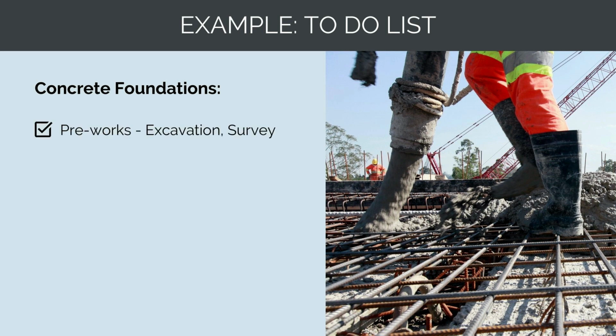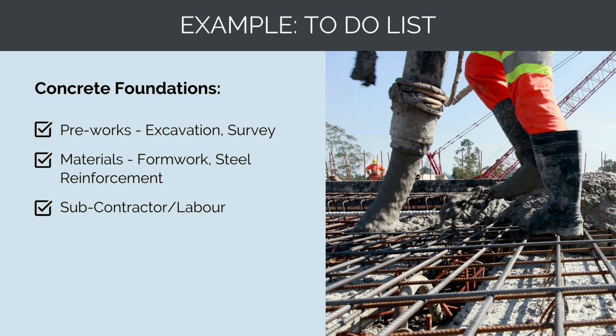So your pre-works, your excavation, you've got to make sure the subcontractor comes to site, or that you coordinate with your supervisors and foremen to make sure that excavations take place as planned. You'll need to call up the surveyor and organize for him to come to site to set it out. You'll need to look through the design drawings and work out all the materials you need. You need to place orders for all the formwork and steel reinforcement. Then for the planned date of the concrete pour, you'll need to work out what labor is available, organize for them to be free to supervise the pour. If you have to book in a concrete pump, you have to call up a concrete pump supplier and organize them for a date to come to site.